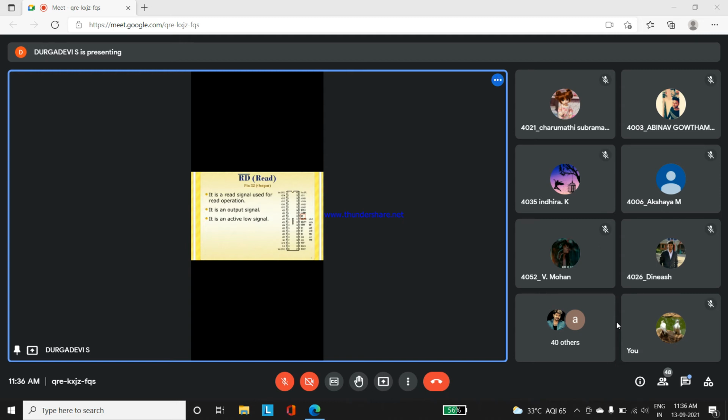See, as a human, you can talk and instruct, whereas a processor and memory, how will they communicate? They will communicate only through the control signals. So memory will see RD bar is equal to 0, and it will understand the processor wants to read the data. For that only it is used.